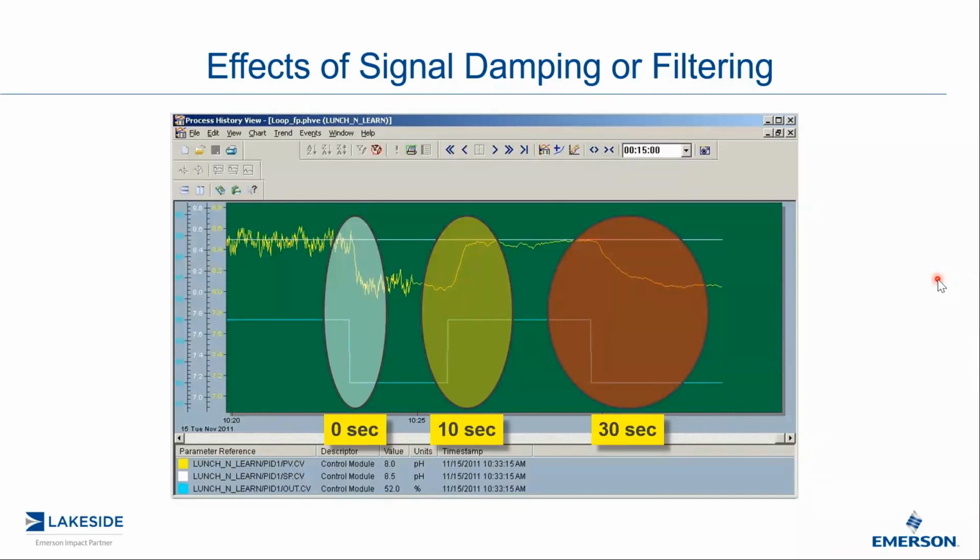A measurement problem. So again, I talked about having a mag meter flanged to an elbow, and I've actually seen that. They actually put a lot of dampening at the transmitter in order to mask the fact that we messed up our process design. And this is what happens sometimes when process people may or may not fully understand the requirements of instrumentation.